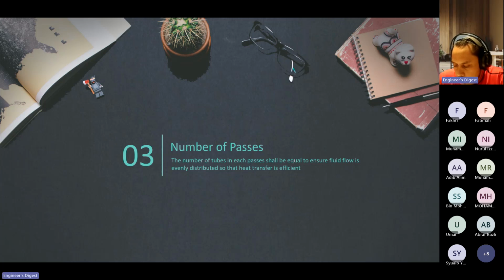If we design with a 10% margin, we can have about 100 tubes that can be plugged at both ends, and this will not cause any issue with the heat duty. However, we need to consult the process team,